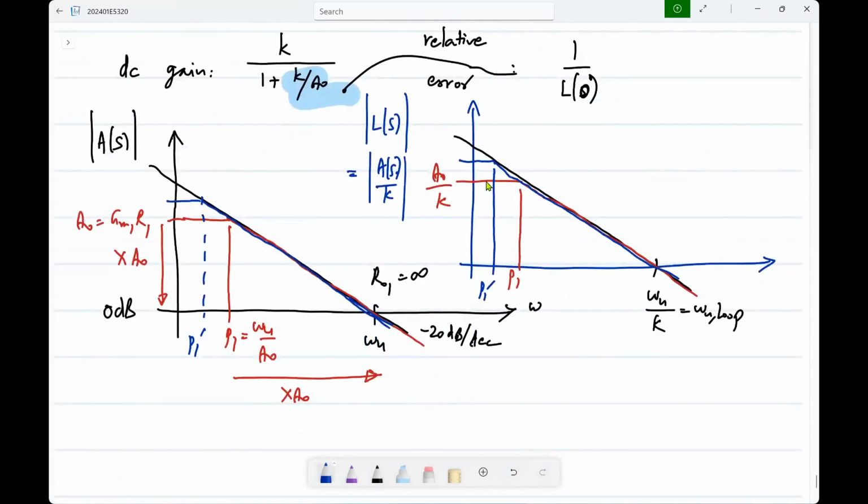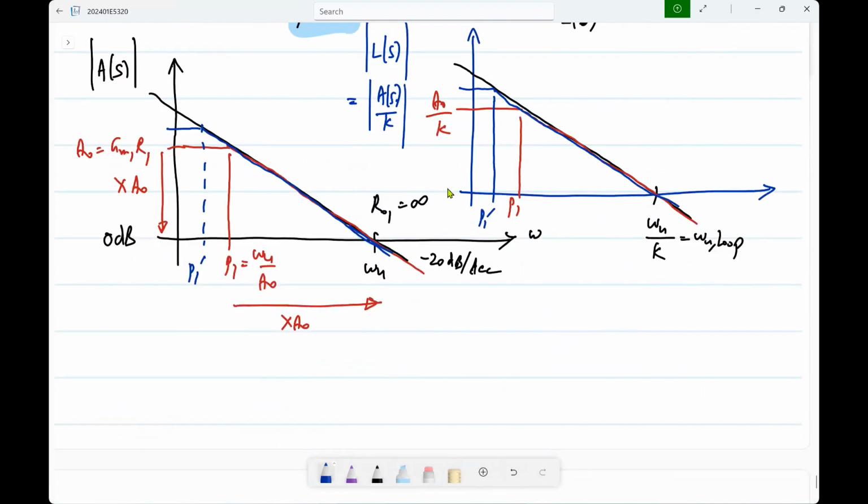So now, of course, the problem is that this DC gain may or may not be large enough. Now it turns out, what is the DC gain of our differential pair with the current mirror load? It was GM1 by GDS1 plus GDS3. Basically, it's of the order of GM by GDS of a MOS transistor.